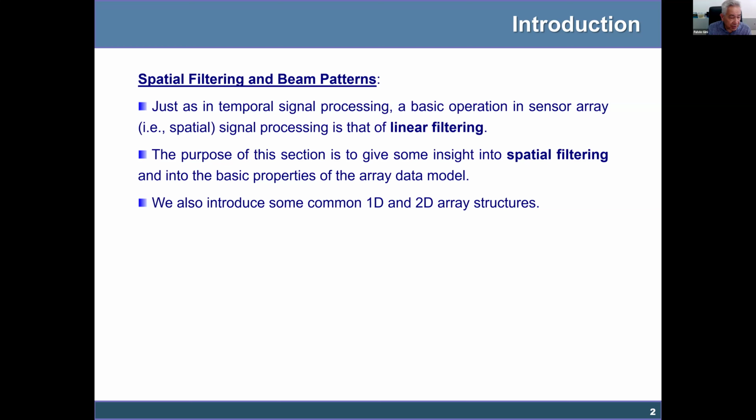So if your signal is a passband signal, for example, with central frequency around 10 kilohertz, the filtering that you typically perform on the signal is a bandpass filter with central frequency around 10 kilohertz.